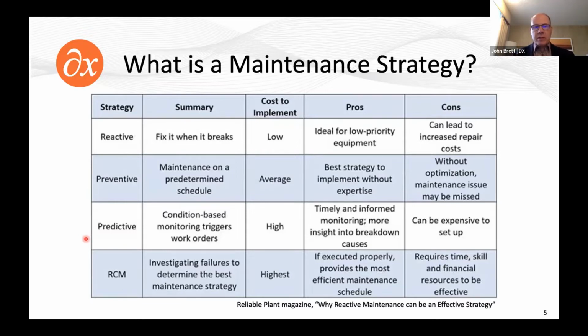Preventative maintenance is just doing stuff on a predetermined schedule. And we're talking about maintenance, not inspection. Inspection is typically also done on a predetermined schedule, but that's to help tell you when things need further investigation. So DGA actually contributes to condition-based, or what they relabel here as predictive-based, maintenance, because you need to constantly be aware of what's going on, understand what the condition is and when it changes, so that you can go and actually do some maintenance.